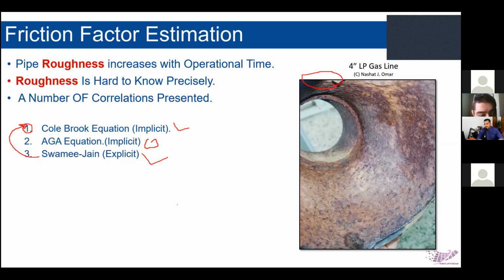Yes. So the uncertainty is related to the corrosion itself, nothing else, like petrophysical properties. And the second one was about injection rate, and you mentioned that you don't have a monitor on the well. Okay, so what I meant by that is that injection wells run on a cheap cost. You need to minimize the cost for the injection well because they are not making any money for us. So what they do not do is run bottom hole gauges for them. You only have the wellhead pressure gauge, so you need to work with that.